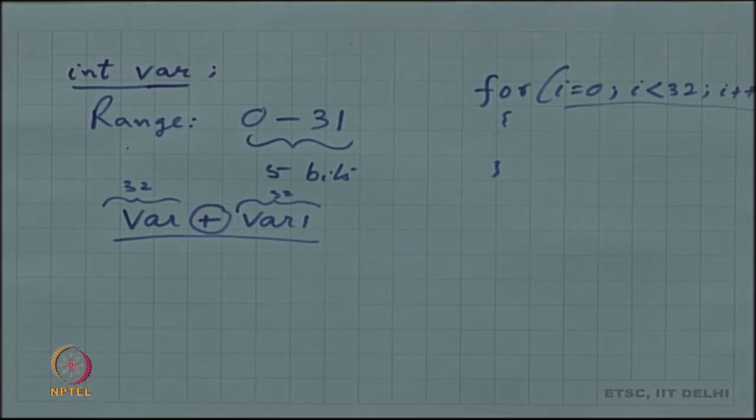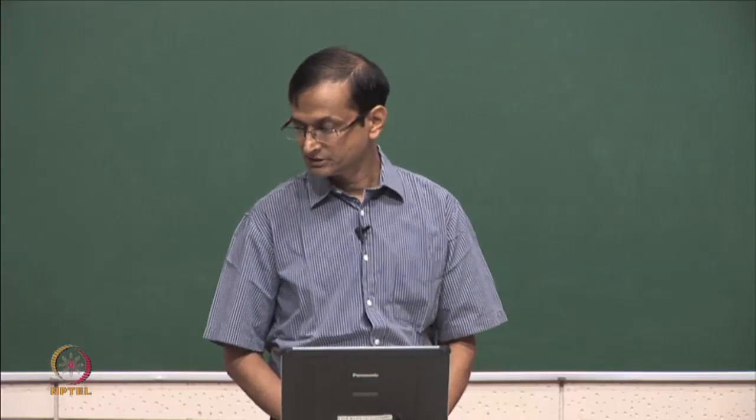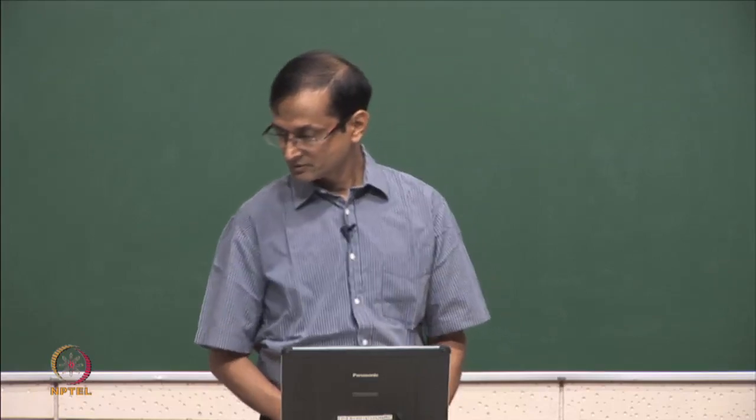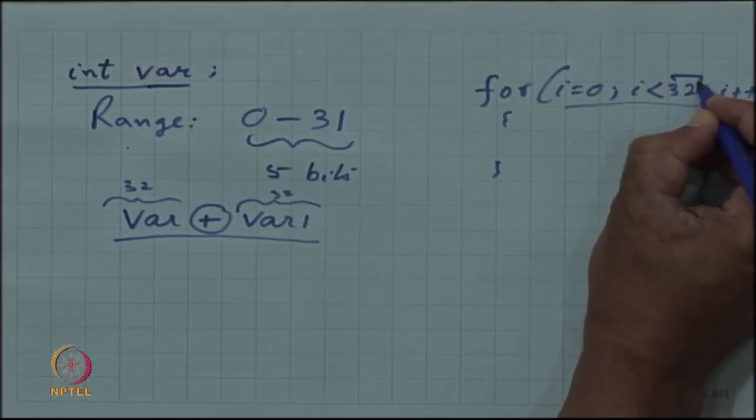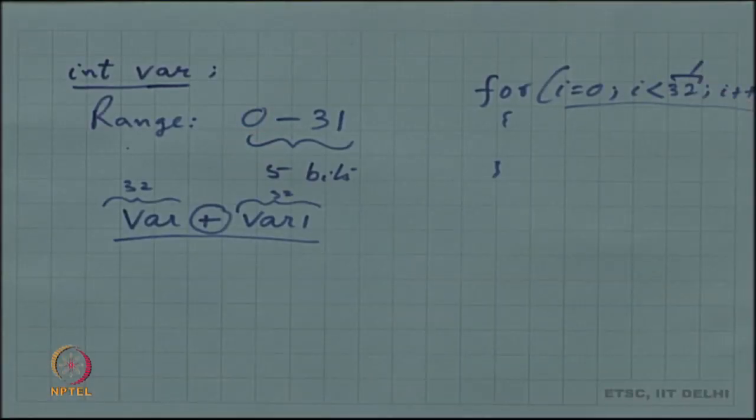Okay. So, if you write such a loop, the synthesis tool could possibly make that inference automatically. Sometimes though, that information might not be there. Sometimes the designer has awareness about the system, maybe that value, instead of being hard coded like that, comes as an external input, and you know from the external working of the system that the value is limited to 32, but otherwise the system might not be able to capture it.